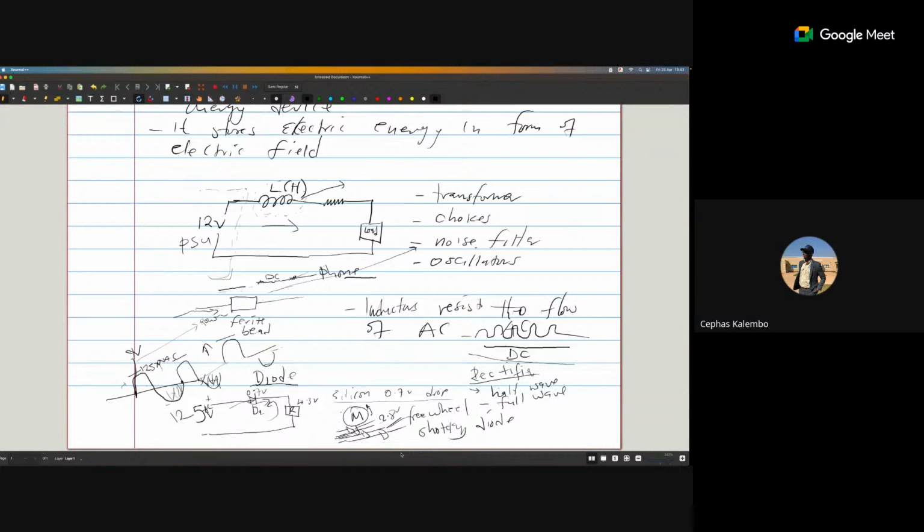Okay. And obviously there's another bypass here that would be like that. So by doing this, it means that we have avoided the cost of losing the flow of that power here by means of this bypass diode. So that's what diode isolation is all about. That's how it works. That is your question.